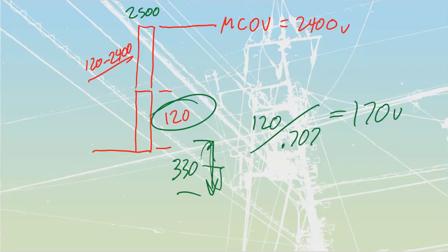Nominal discharge is going to be the peak value of surge current that's going to get conducted through. There will always be a little bit that gets through, but we're not going to allow all of it through. It takes a little bit for even our electronics to react. And then after that, we're going to get into different types of categories.